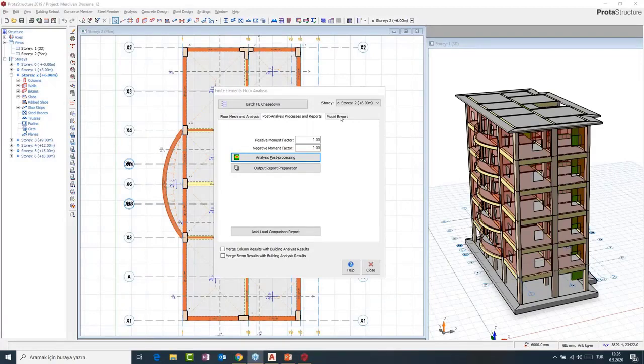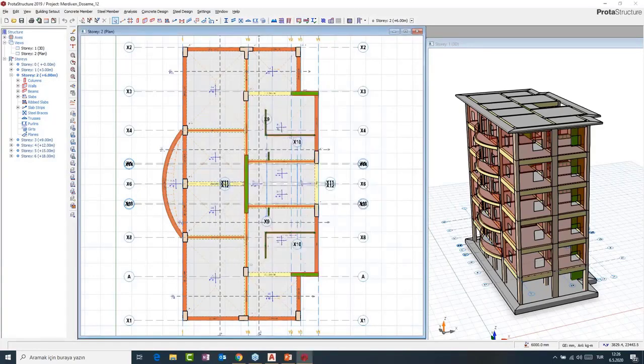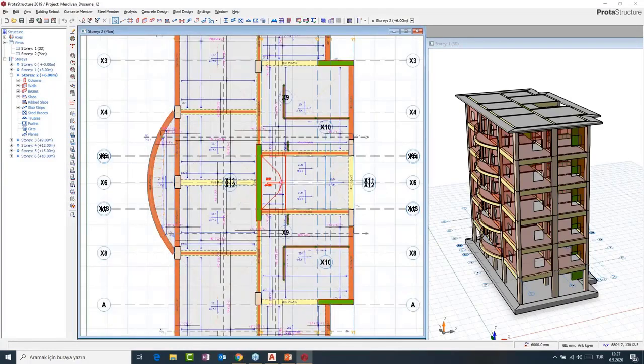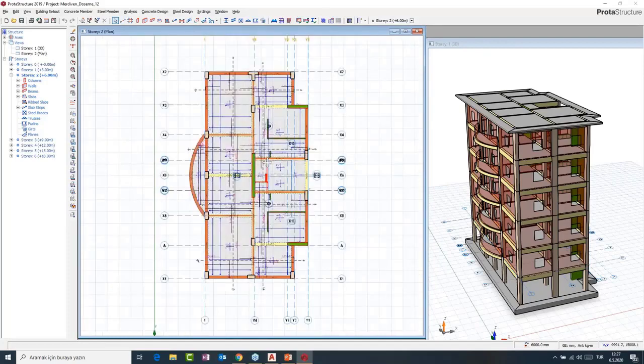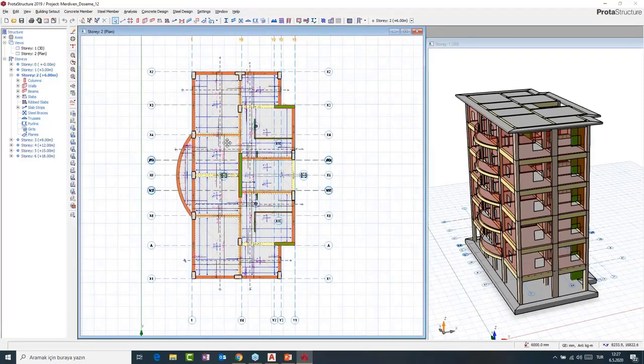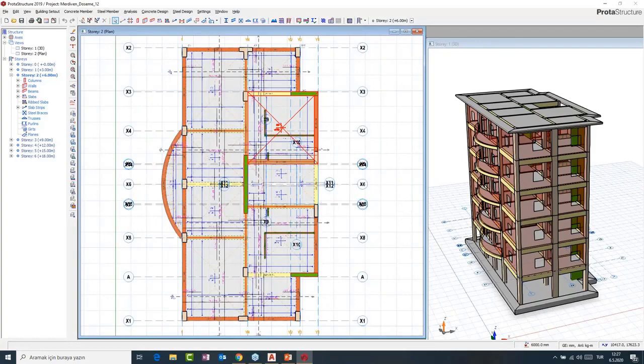And in terms of design, I'm going to come here and right click, and I'll update the steel bars, and you can see the steel bars clearly just like so. Okay. So this is how we do the FE analysis for story number 2. And this is much more accurate than analytical strips. I would recommend doing this in every case. So we can now go straight to our top floor.